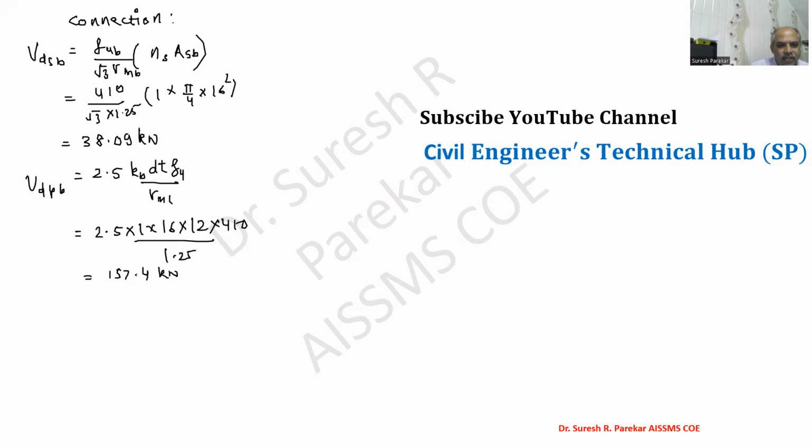Then we will consider Vdb as 38.09 kilonewton, and number of bolts equal to force we have 19.45 divided by the bolt value 38.09. So this is less than 1, therefore provide 1 bolt.